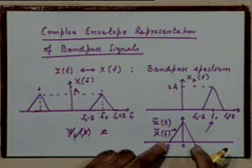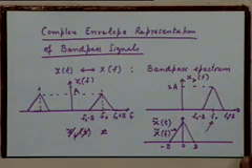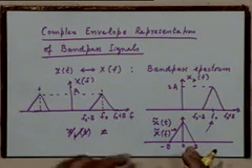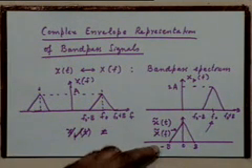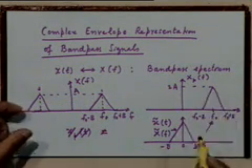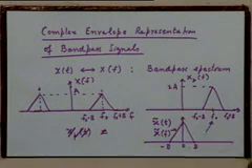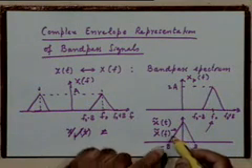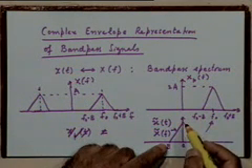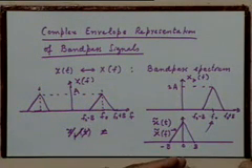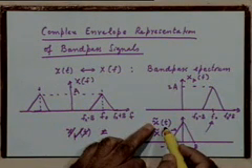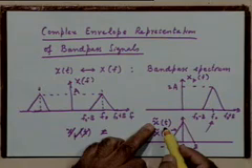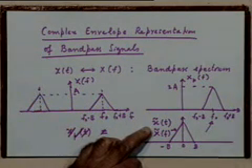This signal is a low pass signal because its spectrum centers around 0, and in general it would be a complex valued signal. In particular it could be real valued if the symmetry here exists, right? In general it would be a complex valued signal, and these two signals would be related by a frequency translation operation. That means xpt would be x tilde t multiplied with e to the power j2 pi f naught t, plus because it's shifting to the right.